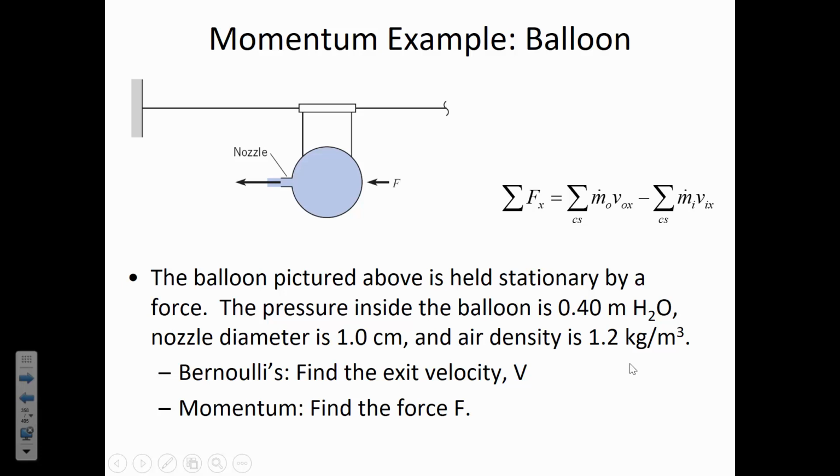So the way that you would get the pressure when it tells you some distance is it means the equivalent pressure at a depth of 0.4 meters. So you just use the hydrostatic equation: delta P is delta H times gamma. When they say the pressure is 0.4 meters of water, they're just saying 0.4 times 9810 is the pressure.